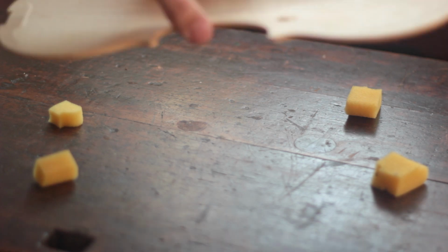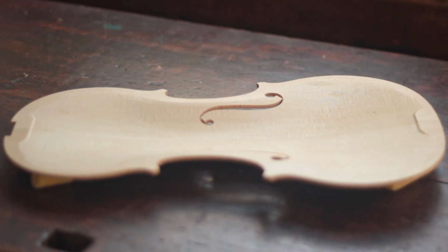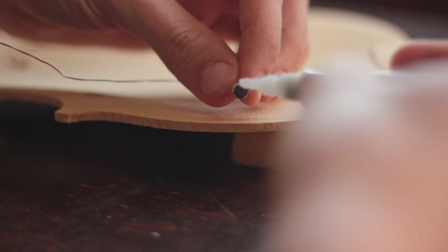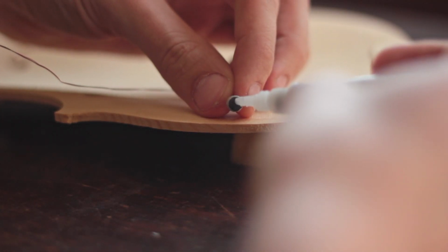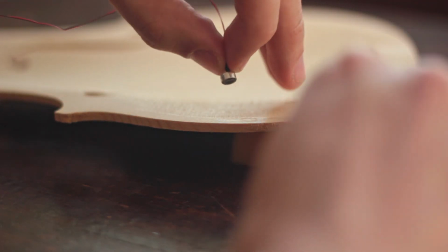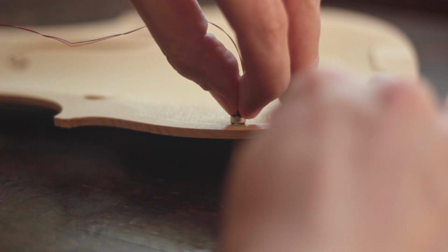For every transfer function measurement, you will want to support the object freely, as we did before. Here I use 4 soft sponges to support the top plate. Then I plug in the equipment and glue on the accelerometer using a small drop of superglue. The position of excitation and recording are important here. If you place either on the nodal line of a given mode, this mode will not be well represented in